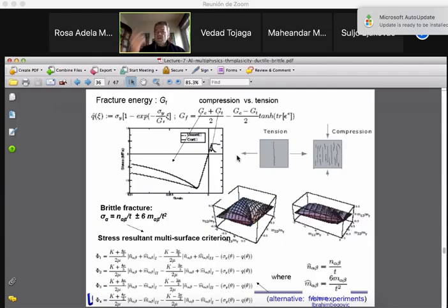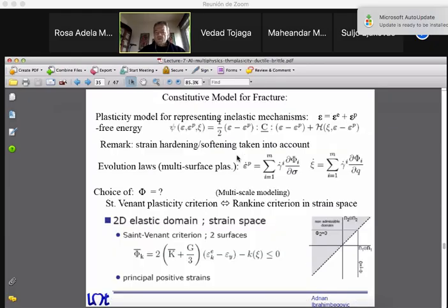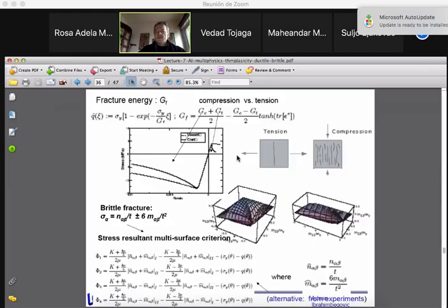I think I already displayed that in the moment. And then you can put it in terms of the stress resultant. So from a full surface plasticity criteria at the level of the strain, that is, you have a first principal strain, a second principal strain for every layer of the shell. You now turn this into stresses, and finally you turn it into stress resultants. Namely, stress resultants are computed under the hypothesis that the stresses are uniformly distributed for the membrane stress. For the membrane forces, these are N alpha beta, alpha and beta being 1 and 2 in direction 1,1, 1,2, and 2,2. So these are like two membrane forces and two membrane shears.